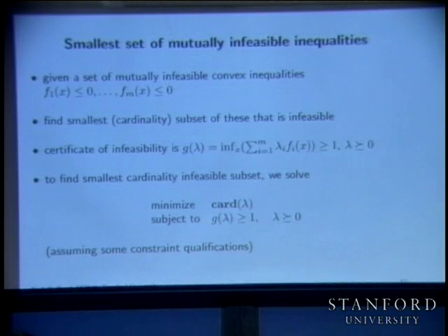If you said, well, I have 28 specs, let's say on phase margin, power, rise time, slew rate, blah, blah, blah. I have 28 of them, they're mutually infeasible, no one can design that amplifier, period. So then the question is what's messing you up?